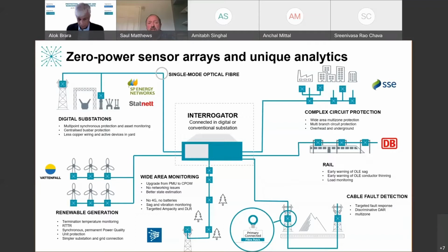In the case of Statnett, for example, we have provided a shadow bus bar protection scheme, independent of the electromechanical standard scheme, where we're able to instrument all of the bays, produce 61850 GOOSE trip signals to operate the circuit breaker, but even with the same system, we were also able to instrument things like transformers and look for problems with vibration and temperature, improving their digital twin accuracy and also generating new condition monitoring data.